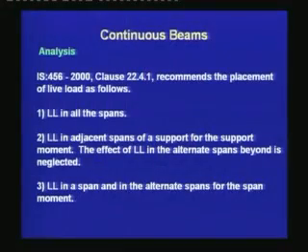The third load case is that the live load should be placed in a span and in the alternate spans for the span moment. To get the most critical case for the span moment, we should place the live load in the span as well as in the alternate spans beyond that. This will give the critical positive moment in the span.